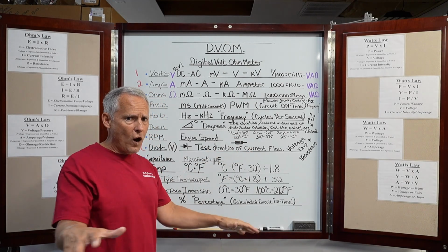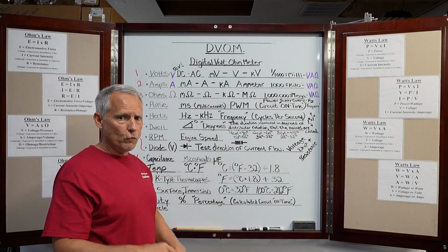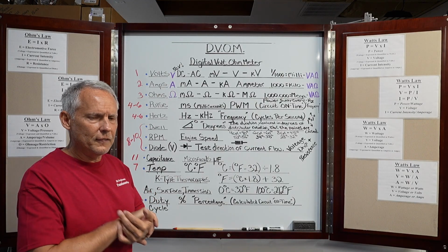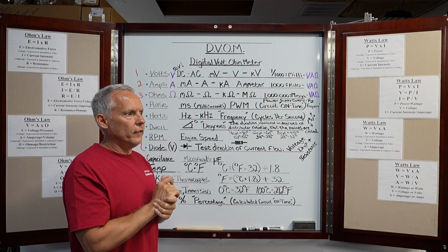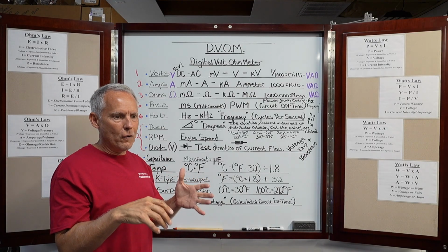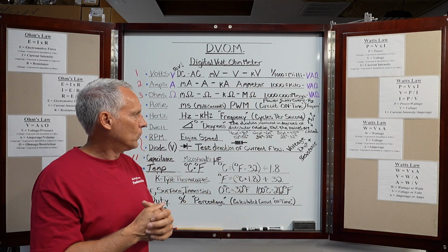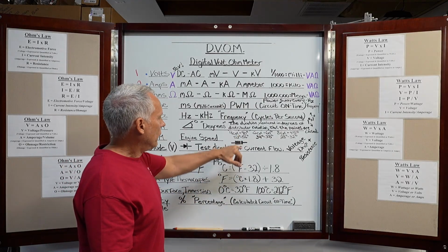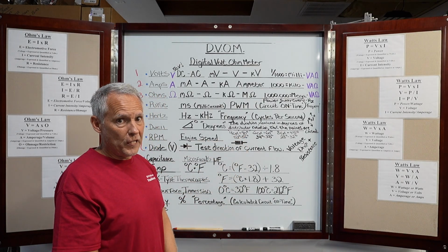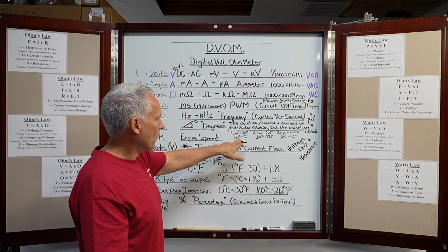Now, like I said, this is way off topic. I just want to touch on it real quick because I've seen posts over the years, and there's a lot of discussion about the point dwell, believe it or not. So basically, this is down and dirty. 90 degrees times 60% is 54 degrees.